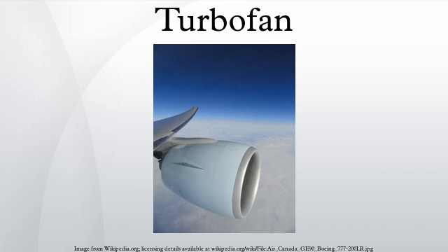Most of the airflow through a high bypass turbofan is low velocity bypass flow. Even when combined with the much higher velocity engine exhaust, the net average exhaust velocity is considerably lower than in a pure turbojet. Engine noise is largely a function of exhaust velocity, therefore turbofan engines are significantly quieter than a pure jet of the same thrust. Other factors include turbine blade and exhaust outlet geometries, such as noise-reducing chevrons seen on the Rolls-Royce Trent 1000 and General Electric GEnx engines used on the Boeing 787.